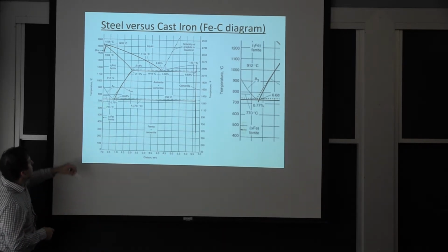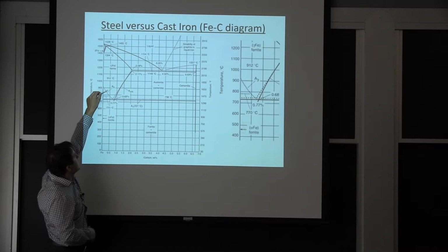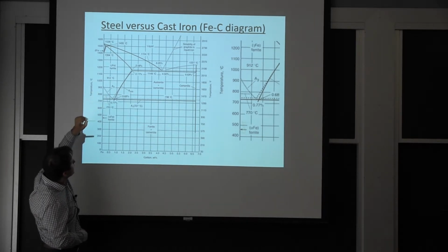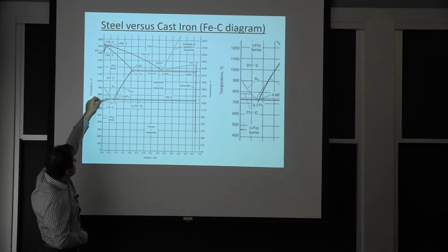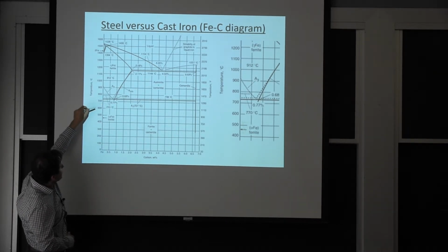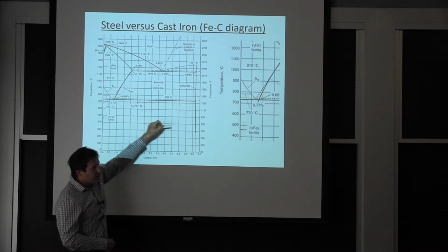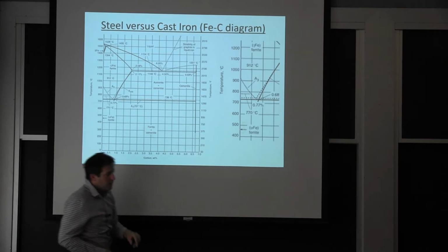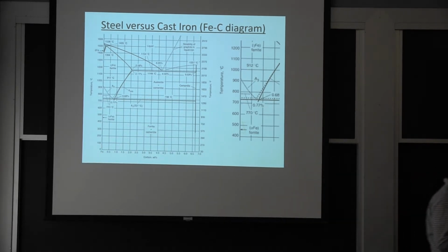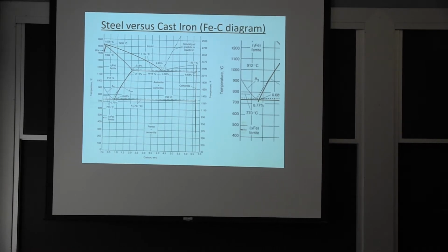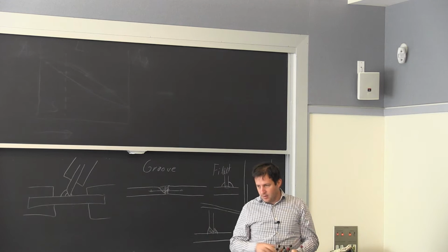So our heat treatment starts in that austenite here, and when we reach the temperature here, around 730 degrees centigrade, is where we're going to form the ferrite, just pure iron, and the cementite if we go slowly. If we go fast, we miss it. So if we go slowly, everything changes in the microstructure from something like this to something like that, and the cementite.